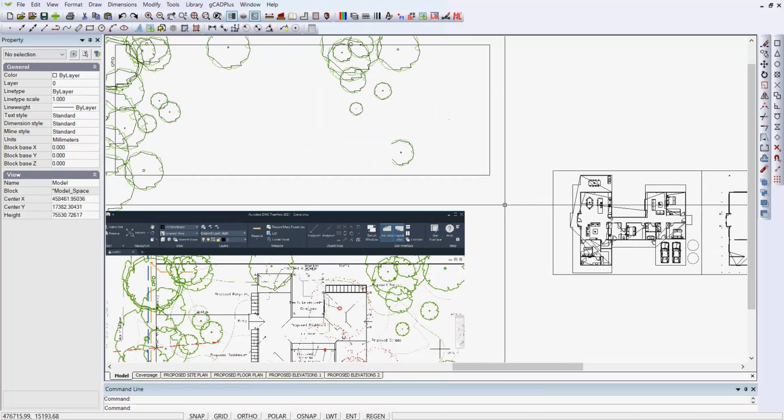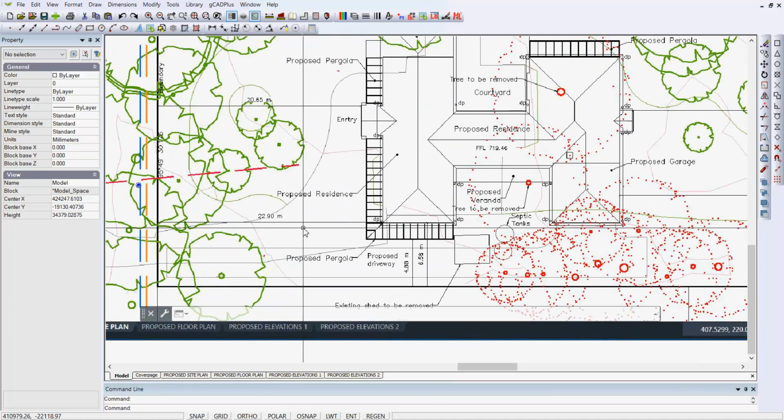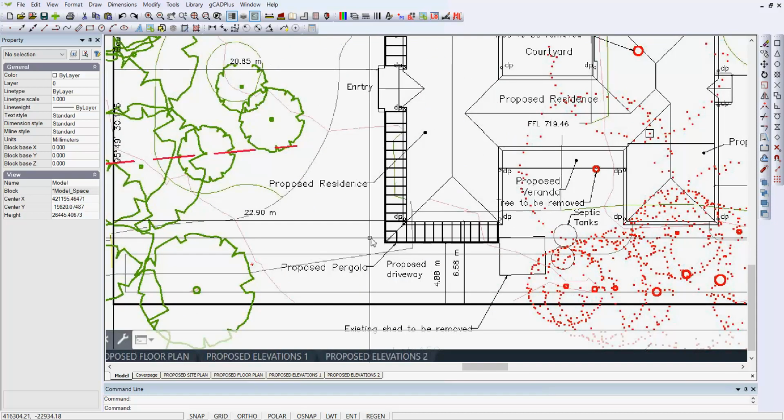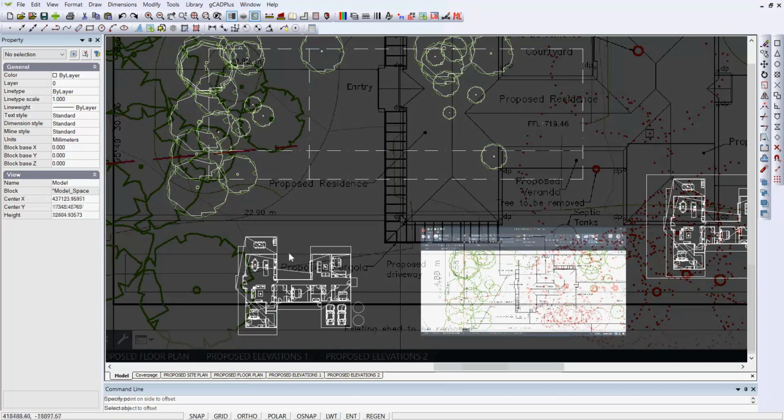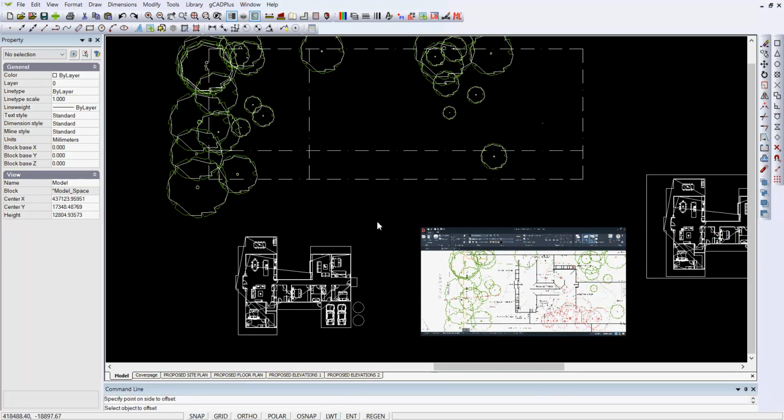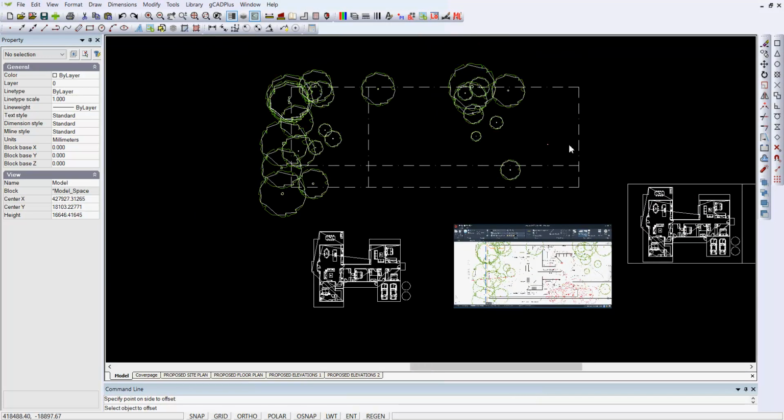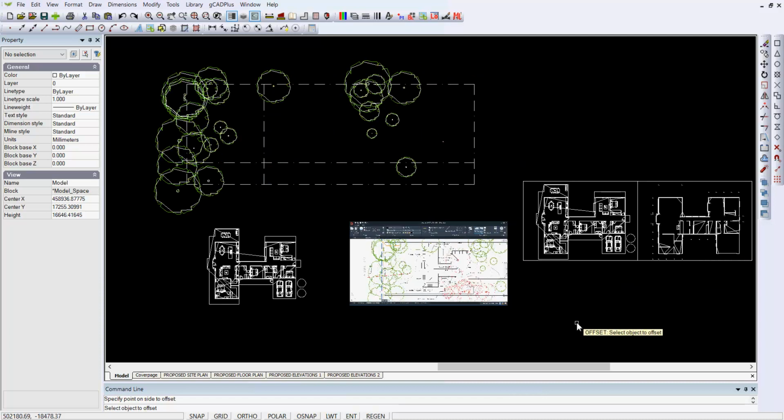So we now need to make a block of the plan and then find in this drawing some information, and we'll be able to site the building plan. But you would recommend, of course, going to the site and just doing some triangulation to check that you've put things in exactly the right place. Well, remembering that in this particular example we were given base information which had a site plan and then over to the right the footprint of the house and so on.